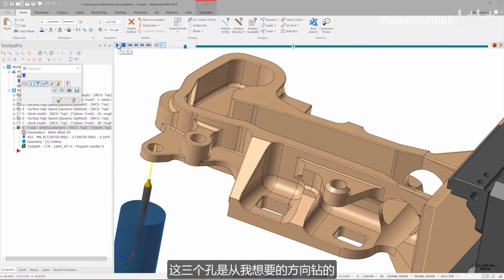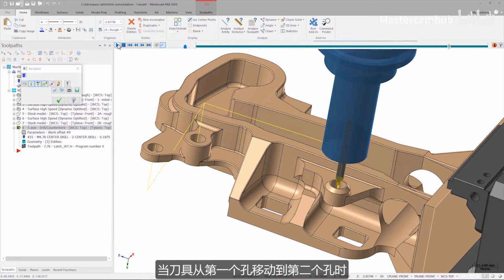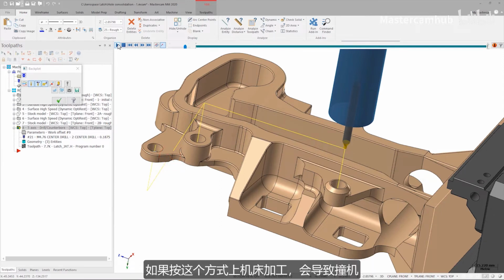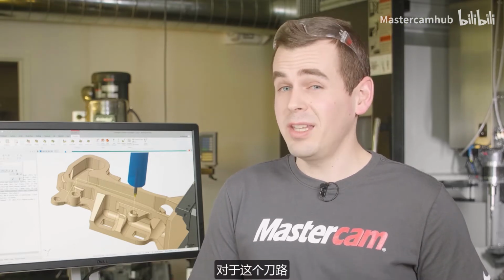The 3 holes are being drilled from the directions that I need, but there is one issue. When the tool moves from the first hole to the second hole, it's moving directly from one point to the next, gouging the part. This would cause a crash at the machine if we were to try and run this code. This is a perfect example that shows you why you should always review your toolpaths in Backplot or simulation before posting them out. For this toolpath, what we want to do is retract to a safe distance, reposition, and then drill the next hole.